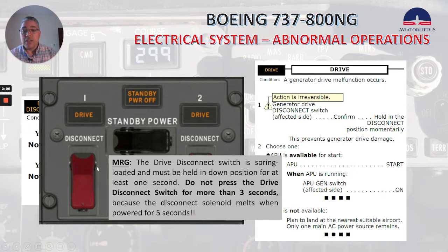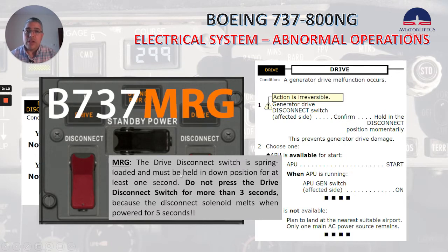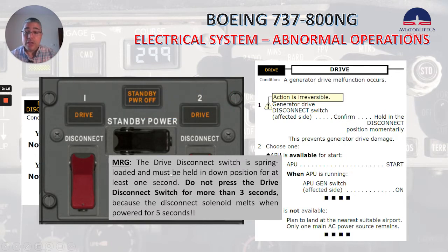Something about the disconnect switch I found in the MRG. Thank you again to Captain Pat Boone for allowing me to use some extracts of his great MRG app. The drive disconnect switch is spring-loaded and must be held in down position for at least 1 second. Do not press the drive disconnect switch for more than 3 seconds because the disconnect solenoid melts when powered for